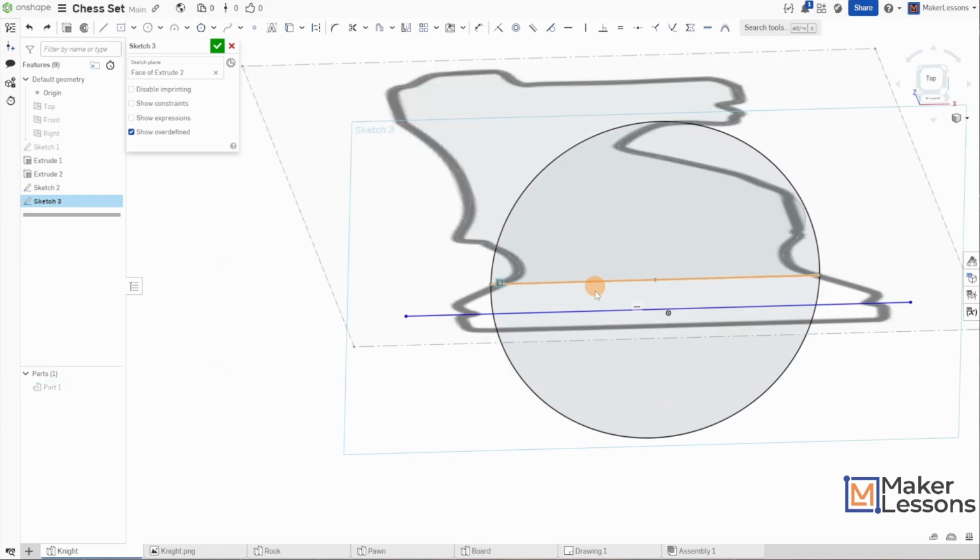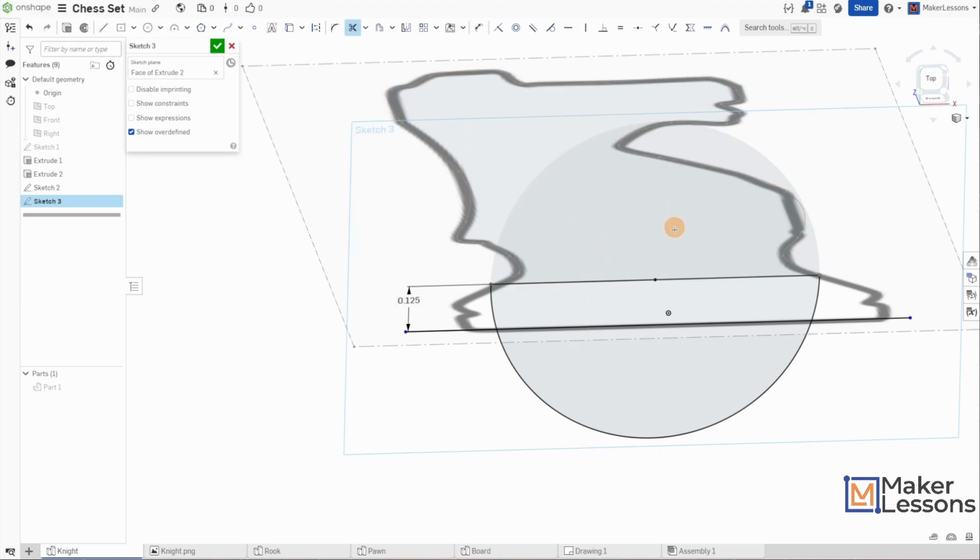And I want to set this distance to a set value. I'm going to make it 0.125, an eighth. So I'll have the whole thing be a 1/4 inch thick. So it'll go on both sides because I'm going to actually mirror this as well. Spoiler alert. So let me trim away all these other pieces. I just want these nubs here.